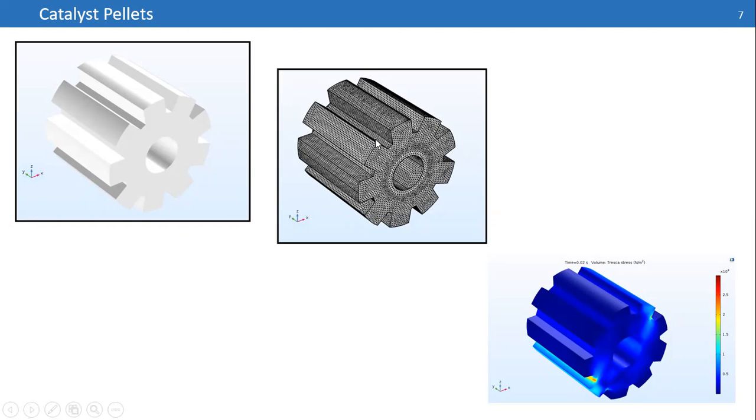So it's very important to investigate your particle in terms of mass transfer, so that gas elements can penetrate inside of your pellet, and then you can have more reaction inside. But maybe in reality, in industrial settings, you have the reaction just on the outer surface of your catalyst.